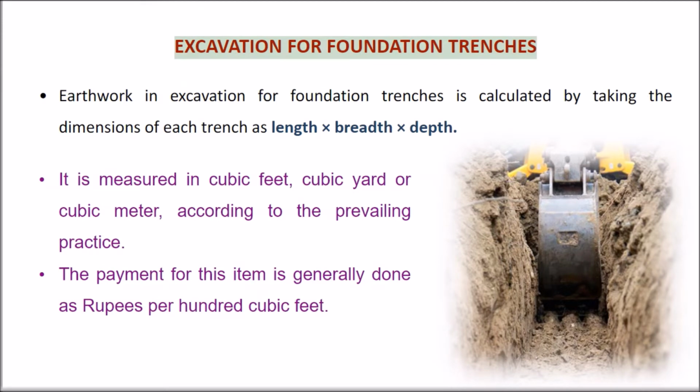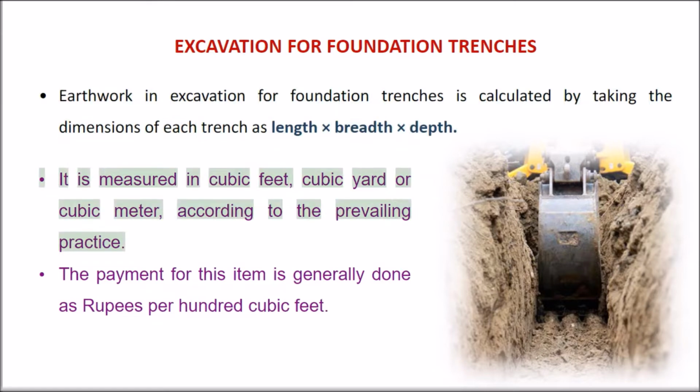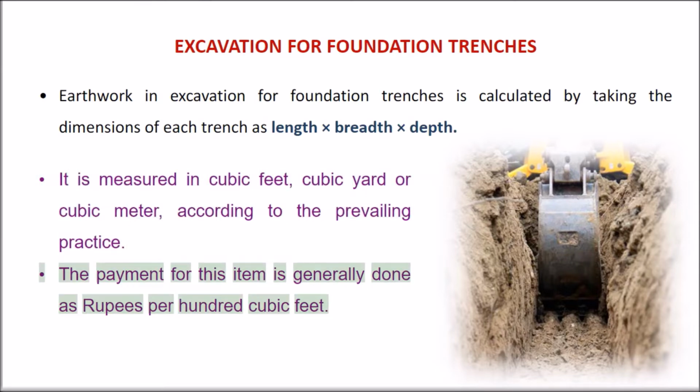Excavation for foundation trenches. Earthwork in excavation for foundation trenches is calculated by taking the dimensions of each trench as length times breadth times depth. It is measured in cubic feet, cubic yard, or cubic meter, according to the prevailing practice. The payment for this item is generally done as rupees per 100 cubic feet.